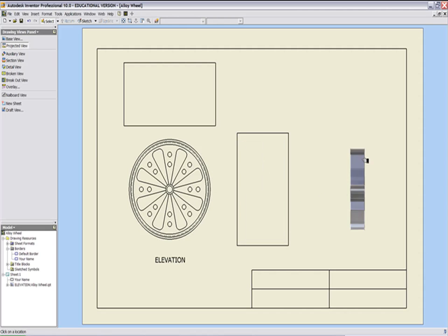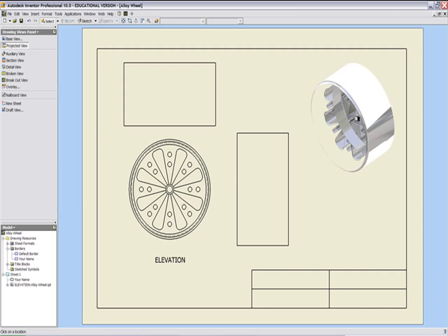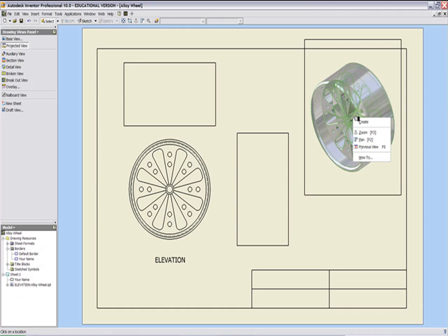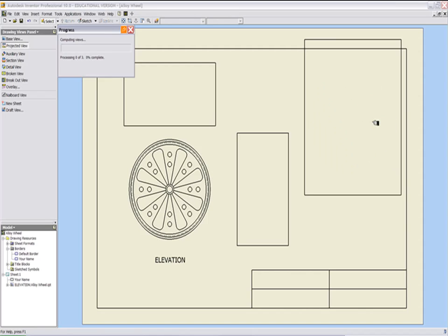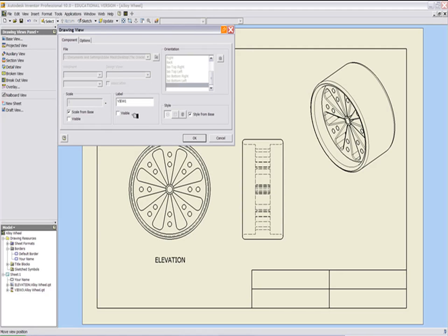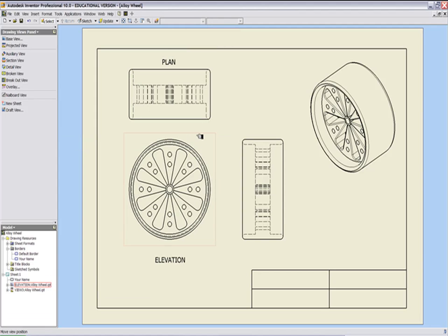Then I'm going to drag up and to the right, I'm going to left click, and now that I've repositioned all my views, I'm going to right click, create, and the views will automatically generate themselves. Minus titles, etc. But that's a straightforward process. I simply have to pick each view in turn, hover to the extents and double click on the red dotted lines and make my changes in the dialog box. Give it a title, make the title visible, say OK, and carefully position the title.